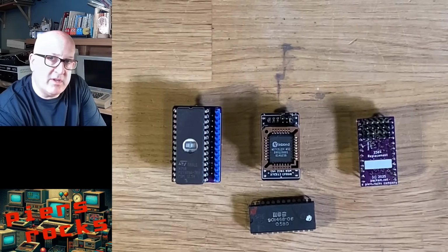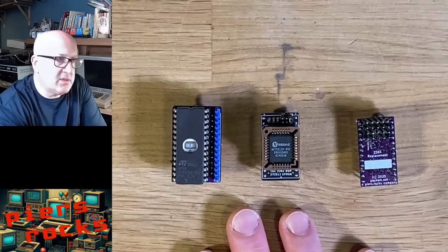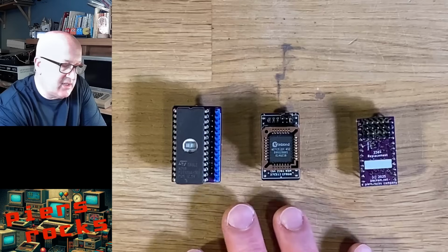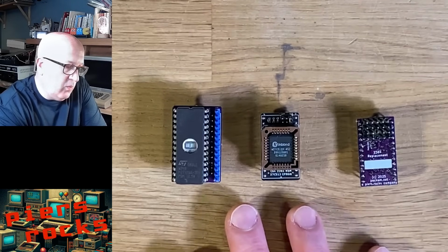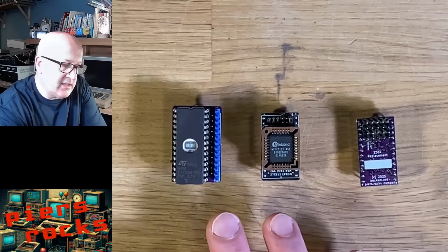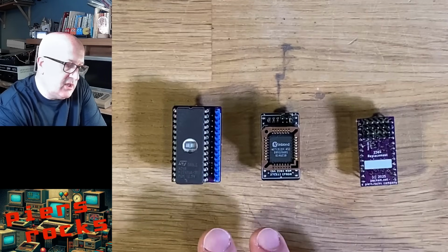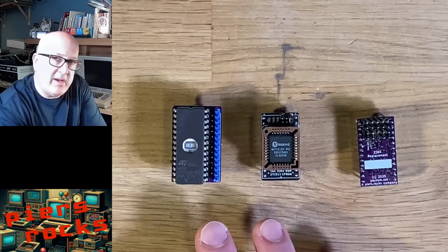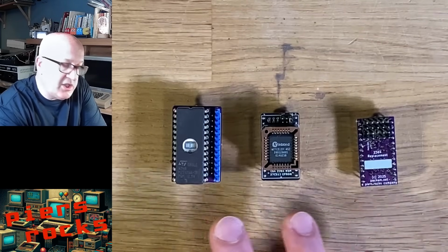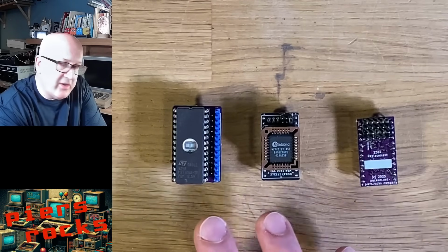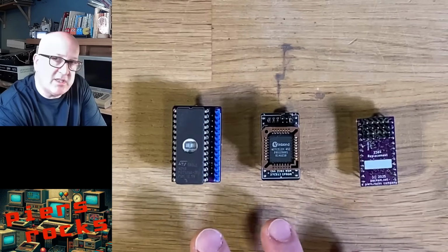Now I've got some typical ROM replacements in front of me, and these are all 2364 replacements, which is what I had to hand. And while these all have a bunch of jumper settings, the jumper settings on these are to allow you to select a different ROM image. So each of these allows you to store multiple 2364 and 2364 only ROM images on the chips that are on board them, and you can select between them with the jumpers, but you cannot change the 2364 chip select